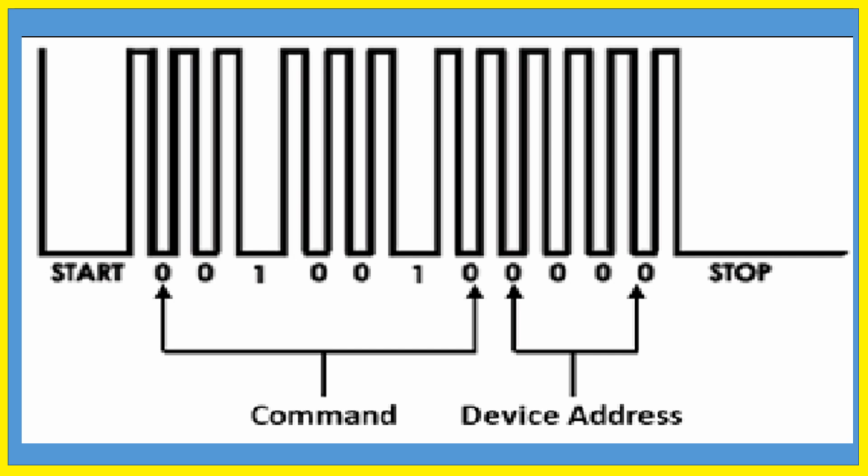The RTU will demodulate it, means they will take this signal, the carrier wave will be bypassed and the CPU will read what it has to do. Then it will act according to the telecommand, means open an interrupter CB or close it, or so many things. So this is the basic idea. I think now you can understand it.